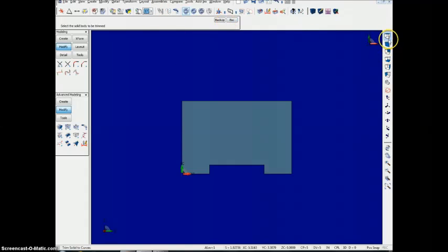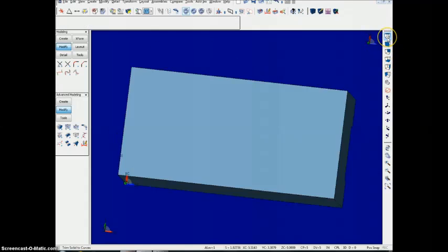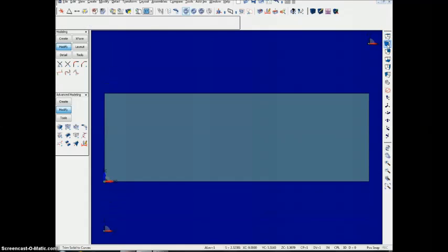Now you can go to the front view, and we're going to do the same thing except just change up the dimensions a little bit. I'm going to change my color so I can see a little bit better. Create line parallel distance, and we're going to go 1 for this, and we're going to go from the left and the right side and up 0.5.